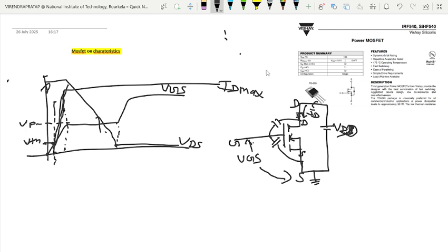And this time is called delay time. This delay time depends upon the input capacitor of the MOSFET. Suppose that this is the gate resistance, this is CGD, CGS. Basically, the delay time is the time to charge the MOSFET input capacitor. To charge the input capacitor, it will take time, TD. We know very well in an RC circuit. I will explain later how this delay will take time.